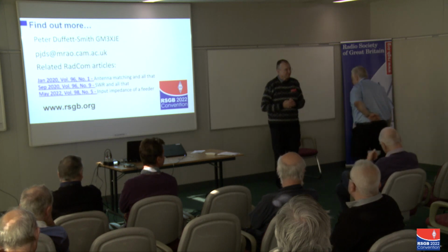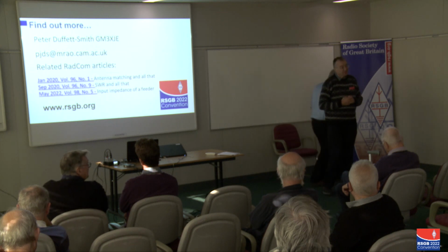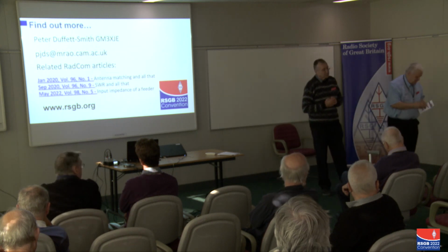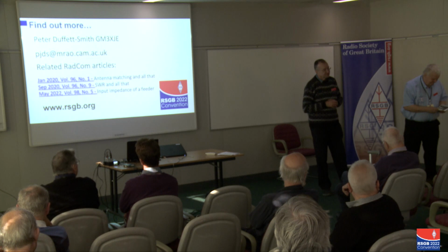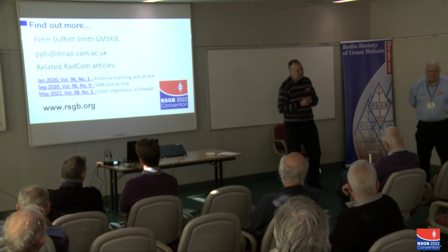Hello there. I just want to talk about velocity factor of different feeders. Yes. Now, basically, is that almost like a speedo, could we say, for the RF? Exactly that. The velocity factor of radio waves in free space is 1, because it is the velocity of the waves divided by the velocity of the waves in free space.